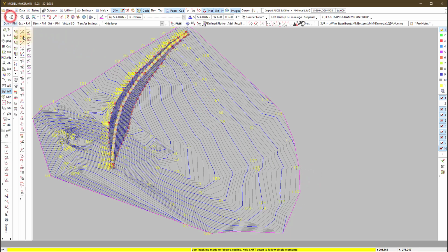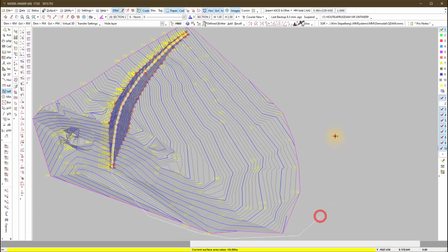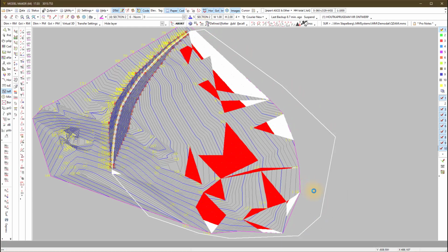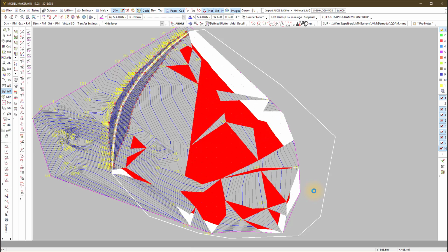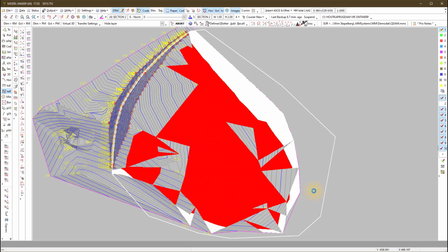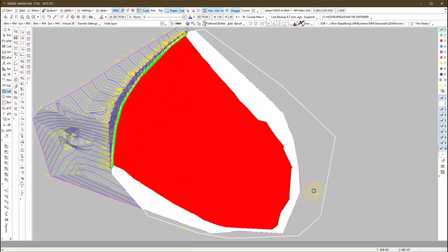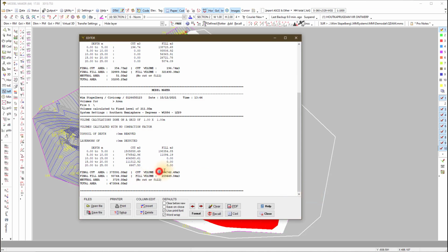So okay, indicate an area, define the area. I'm just gonna refresh my screen, and then in the center of the wall I go down there, just freehand snap, and then just on the outside of that 211 contour on the water side. Then if I escape, I say accept. Wherever the red is, that's where the water is going to be, so it's the cut volume that I'm going to use. And that's going to give me my water volume.